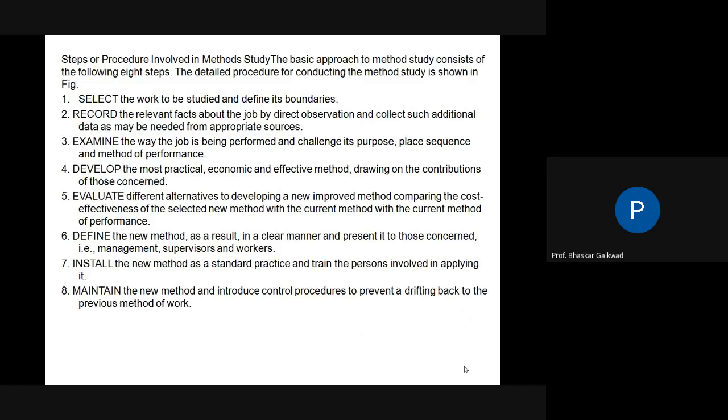So first you can study the drawing, then you can make the program as per the dimensions. Study the geometrical and dimensional tolerance. After this, you can make the program, feed this program into the machines. Then we can hold the raw material in the chuck of the CNC machine, make it zero, and start the machine. The cycle time will start. Within a few minutes, the job will get completed.